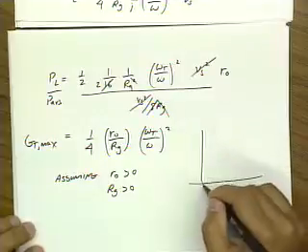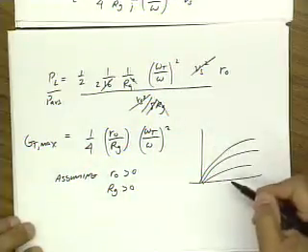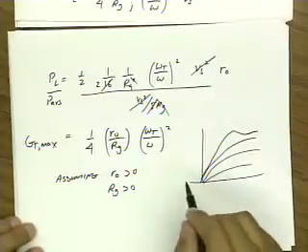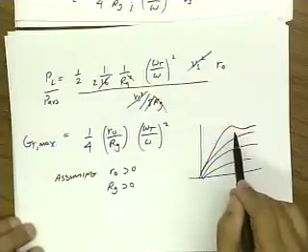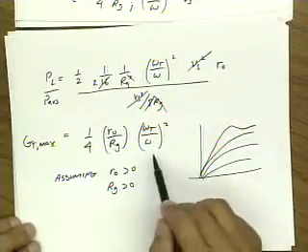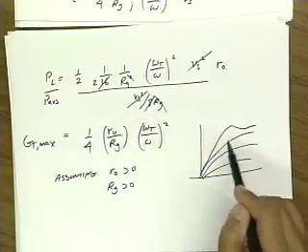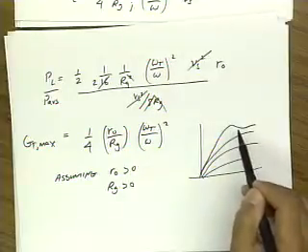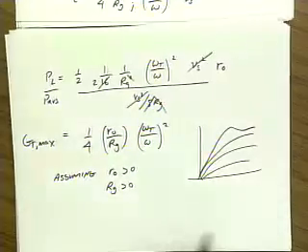So for instance, if we look at our curves, if this slope is positive, that means that Ro is positive. But what if you had a weird kink in your curve, right? At this point, Ro goes negative, and that means that actually GT max, as we've defined it, doesn't exist. Because the device, under certain conditions, you can make the device oscillate in this region. Okay? We'll have a lot more to say about that later on.